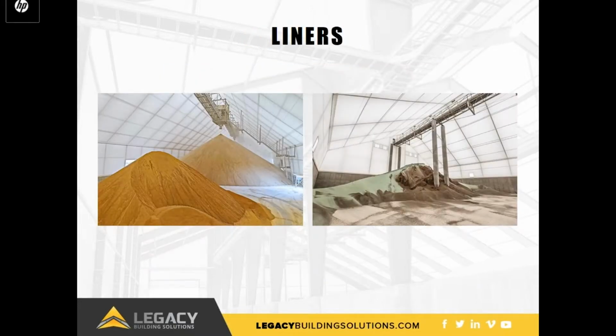Uninsulated buildings may also be lined for corrosion protection. Structural fabric, including Legacy's exclusive EXXOTEC PVC fabric, is non-corrosive. Adding a fabric liner to the underside of the frame keeps the steel frame out of contact with all corrosive elements, including salt, fertilizer, and moisture. This is a cost-effective alternative to epoxy paints that are often used to stop corrosion, and a permanent alternative that is not subject to pitting or thinning when exposed to corrosive elements.